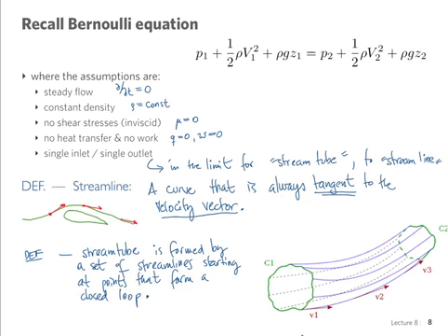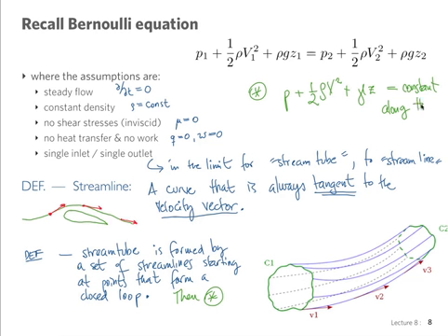So then we can write another form of the Bernoulli equation for this situation. I'm going to write here, Bernoulli equation for that case: P plus 1/2 rho v squared plus gamma z, where I've written rho g as gamma, equals a constant along, well, I'm going to now make that stream tube infinitely thin, and it's going to be along the streamline.